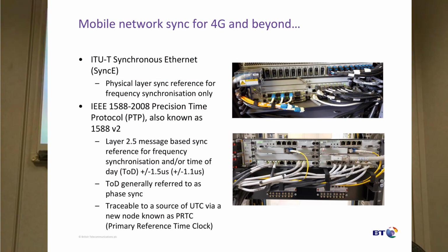So, firstly, how do we address the frequency synchronization? Well, I mentioned before that some of the techniques associated with TDM and the E1 frame we would find ultimately in the carrier Ethernet world. And we do that through something known as synchronous Ethernet, or SyncE as it's commonly known. This was a specification developed by the International Telecommunication Union, the Telecoms division, where a physical layer sync reference was implemented on the actual physical transmission, so using the line code in the same way we do with the HDB3 on the E1, to actually recover a frequency reference.